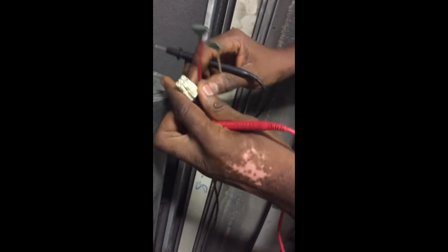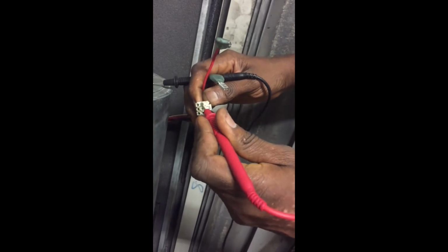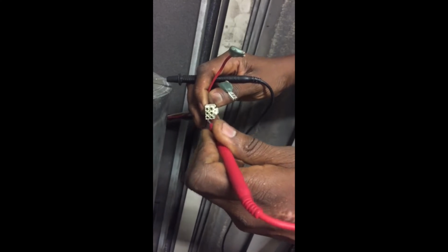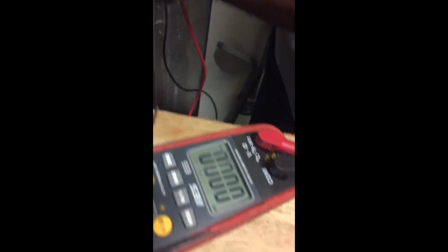How do you confirm this? The common that you have here remains common for everything, which is our blue. So remember, common to run always has a lower resistance compared to common to start. So we are going to identify which of these is run and which of these is start. So we just get the probe on the common and see between these which is having a higher or lower resistance. Put it here. What are we getting?